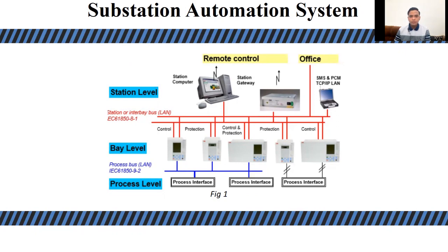Automatic substation monitoring and control via intelligent electronic devices or IEDs and a communication network consists of SAS. Through a centrally located server and workstation, SAS uses the functional capability of IEDs to implement automation, protection, metering, control, and monitoring. It is designed to facilitate control locally from within the substation and remotely from the utility load dispatch center or load control center. Figure one shows a simple block diagram for a transmission SAS.